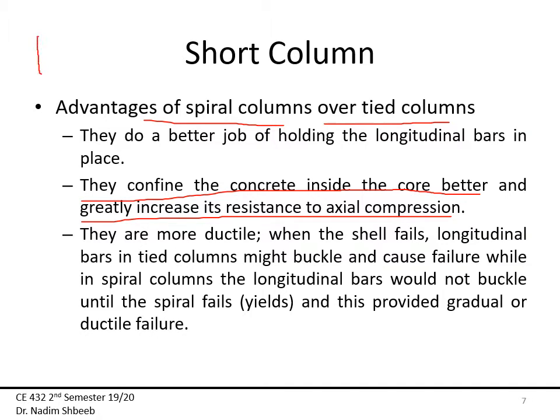So let's say I have a cylinder, and assume that I'm filling this with sand. Sand in itself, if I apply a load to it, will collapse immediately. But if I put that in a cylindrical container, and let's say I'm applying a force P, obviously if it's loose sand, it will become dense up to a certain point where it achieves maximum density, and then the sand particles don't have any place to go. So what will happen then as I increase the load?